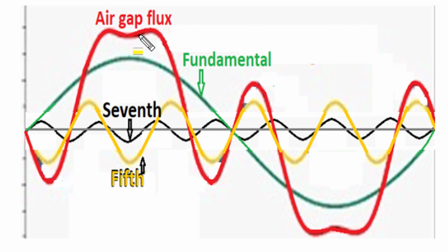And such non-sinusoidal flux can be considered as a fundamental sinusoidal flux distribution, which with peak magnitude in one direction represents one pole effect, and similarly peak magnitude in the opposite direction produces another pole. So if a fundamental flux MMF distribution produces two poles, and there are no even harmonics or triple and its multiple harmonics, then we would have 5th, 7th, 11th and 13th harmonic flux distributions.